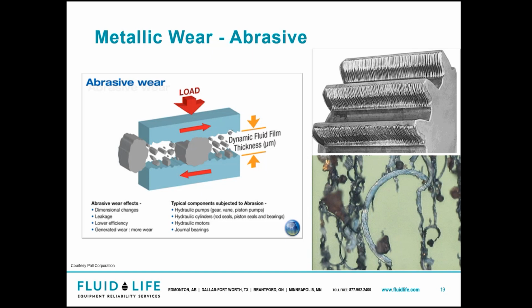Now, what'll happen is, again, a hard particle gets in there, and it's just going to gouge out the material from our components. Very common in something like a gearbox. And again, gearboxes are designed to shed that material. That's why we have things like mag plugs, and why we should be filtering our oil. And for those who attended the oil sampling session, that's why we don't sample from drain plugs, because all those particles are just going to sit down there, and you're going to have very erroneous results with your samples.